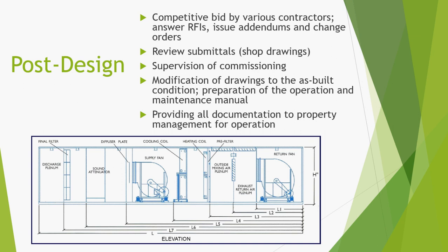After a contractor is selected, all document revisions are modified with change orders. Change orders are undesirable because the contractor states the costs increase or decrease, but with no competitive pressure. Before equipment is ordered, the engineer is responsible for reviewing submittals, also known as shop drawings. This helps ensure that the equipment installed matches the engineer's intent.